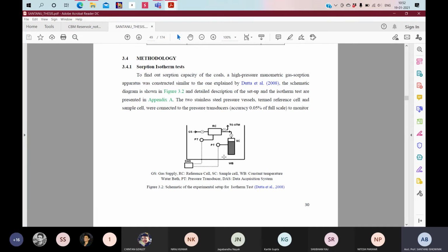If you are not going to allow some time, it may happen that the moment the oil and water bath circulates, the total area is not streamlined at 30 degrees centigrade. Some part is going to show 30.1, some part is going to show 29.9, and this will put in error, because the Z factor, the compressibility, is very sensitive to temperature and pressure.